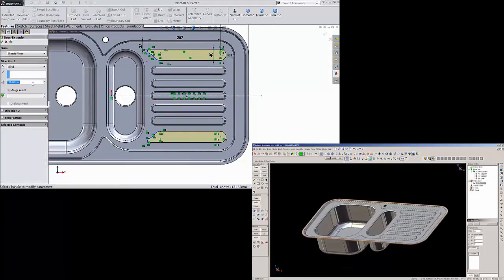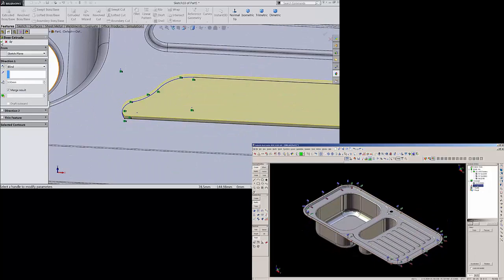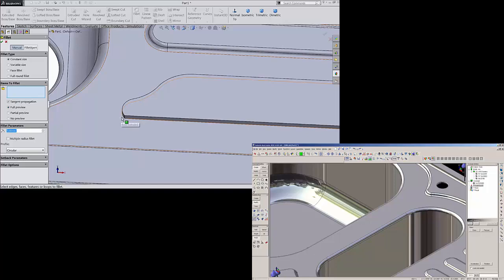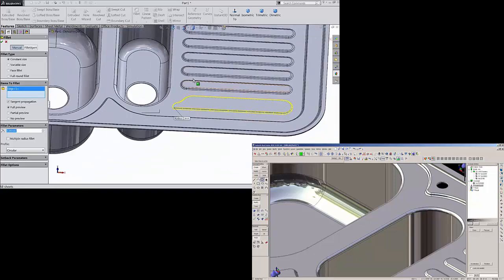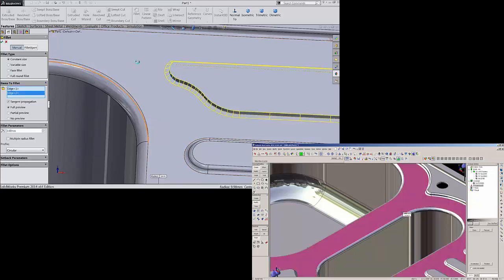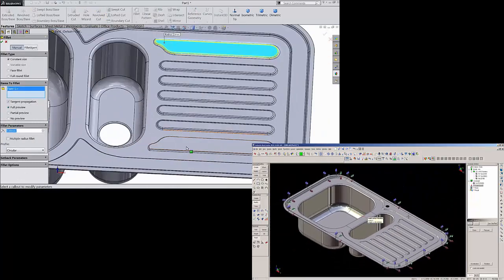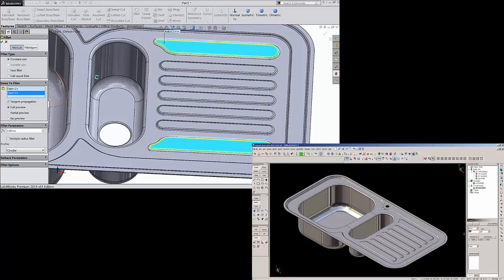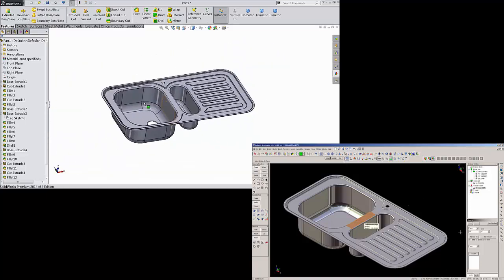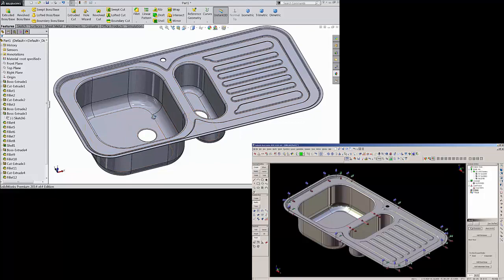Now select extruded boss and extrude up to only 3 mm. That's it, not more than that. Okay. Keep fillet. Select bottom edge 3 mm. Okay. Now again keep once more fillet 3 mm and select the top face. Okay, top faces. Now our basin is ready. This is the wash basin. This is a 2 chamber basin. One is small and one big.